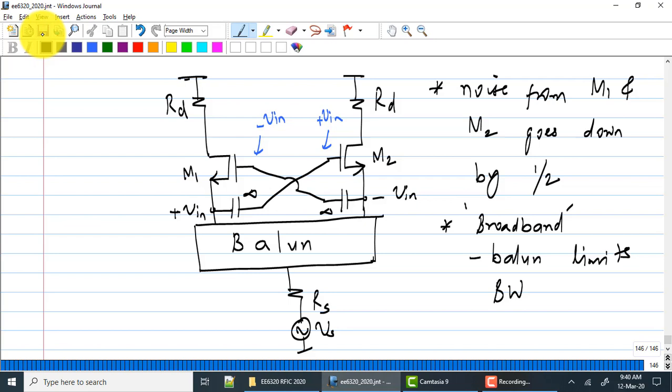Why would it matter? Actually, it won't matter. You're only trying to make output resonance, right? You're not applying any common mode signal, so it won't matter at all. For the differential circuit, it will be exactly the same whether you connect the two of them together and connect them to ground, or just use one single capacitor of half the value. As far as your differential input is concerned, it will be exactly the same. Correct, but I have not asked you to do anything for the common mode.